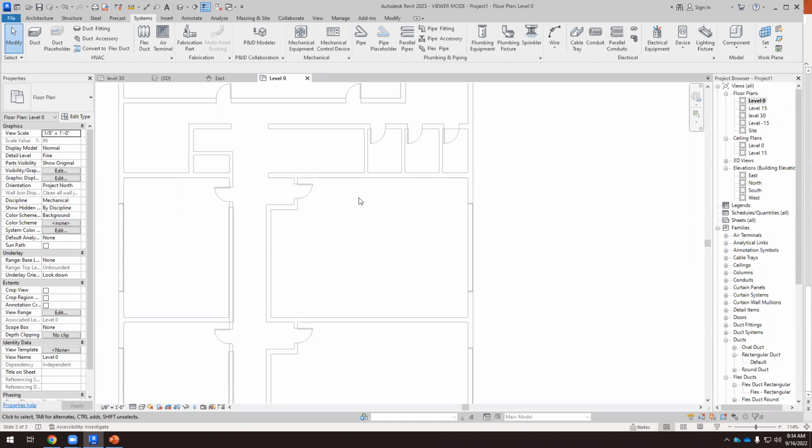I'm not worried about conditions here, because people are not living above this limit. It's very unlikely that there's someone taller than this. So I'm not concerned about the thermal conditions there. I'm concerned that all my sensors of temperature and relative humidity will be here. Okay, so those are the sensors, they have to be in the occupied area.